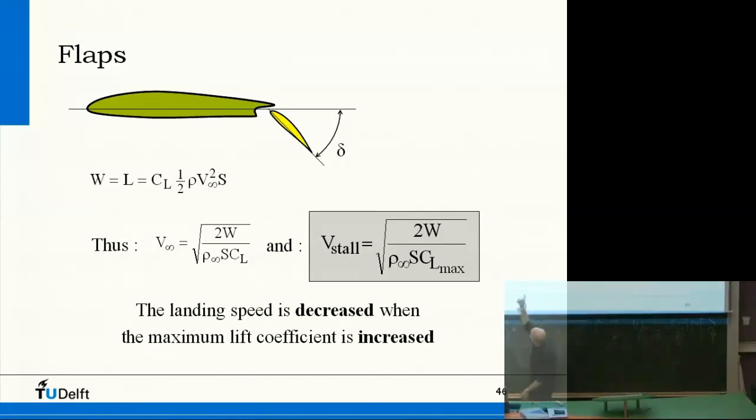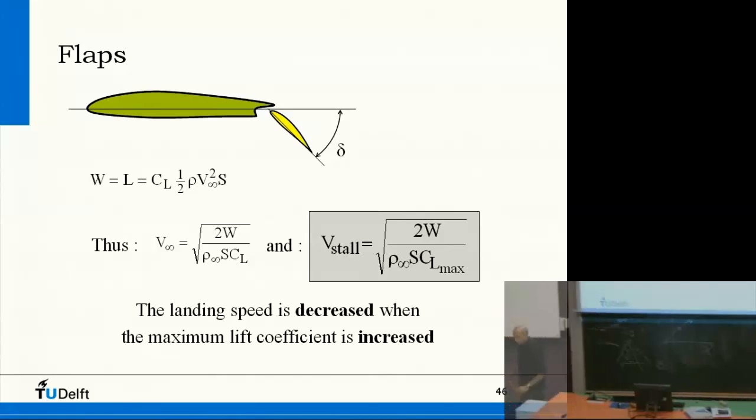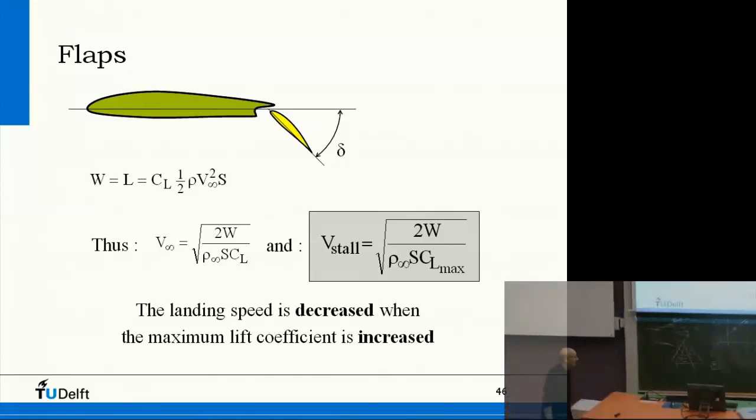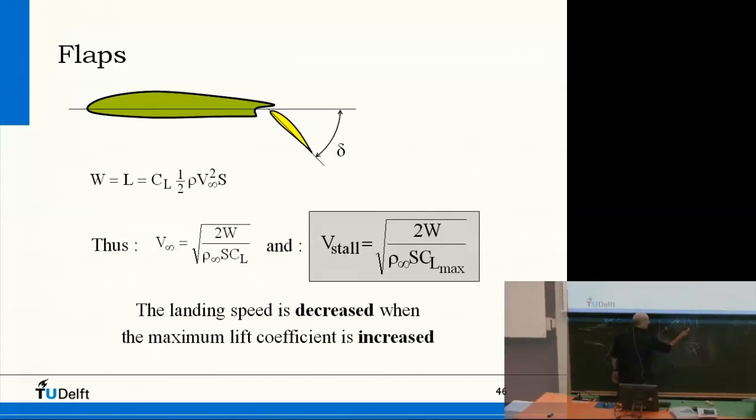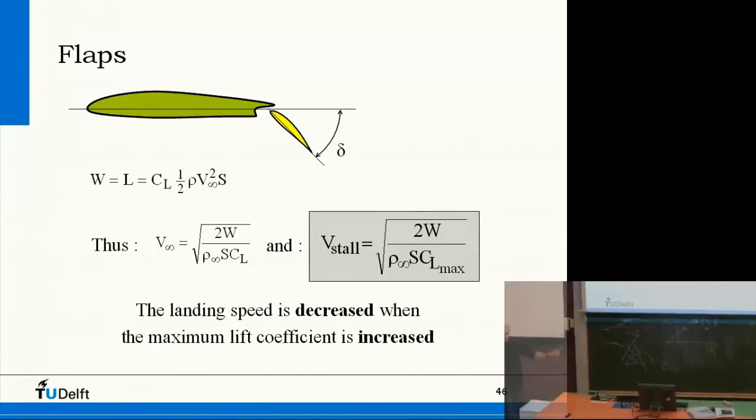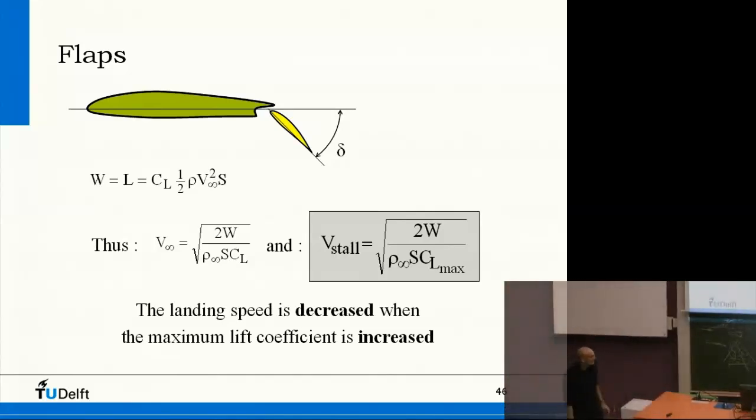Well, from this equation, of course, you can make an equation for the stall velocity, because this is something that you should avoid. No matter what you do here, increasing the angle of attack is not going to help. The CL stays down, right? So you should not cross this one here. And in the cockpit, you see all kinds of signals when you approach this CL max.